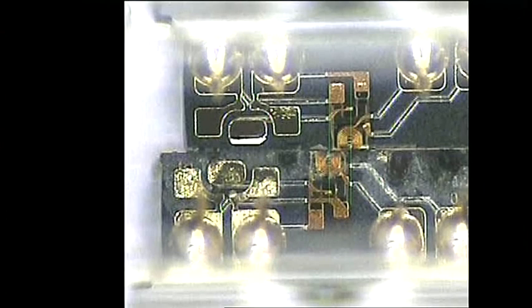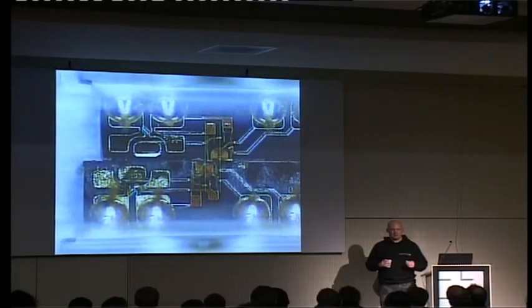Well, maybe I have to tell, in a hard drive with more than one head, there's always only one head actually activated and connected to the preamp. The preamp is the preamplifier, which amplifies the head signal from the MR read element. And that actually gets, by a little interface, set the number of the head it is supposed to select.